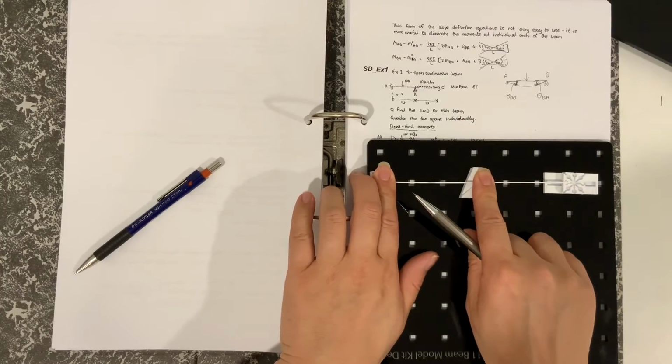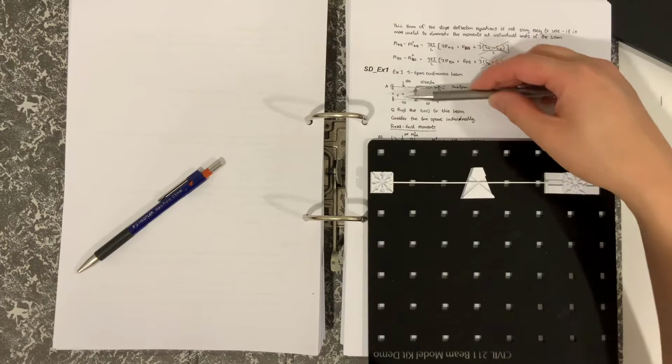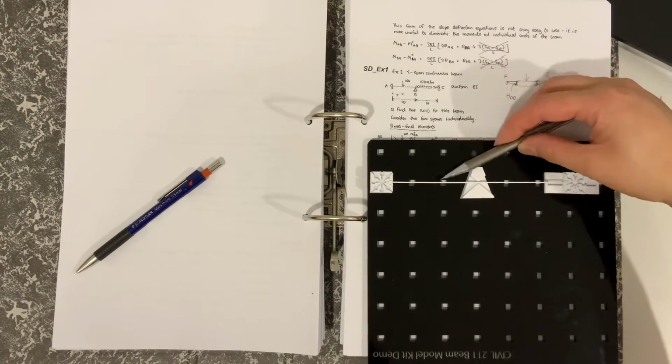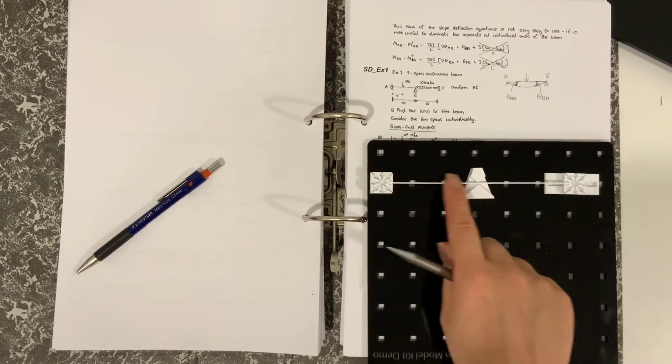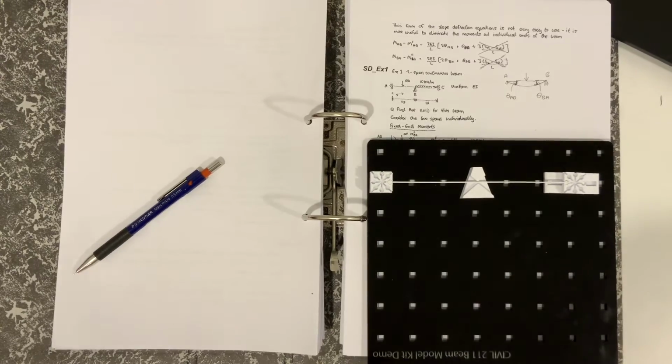So in this case here, we've got 100, so we keep the same span, which would be AB, and we keep the same load. The important thing when you work out the fixed end moment is you keep the same load. If there's no load acting on the span here, then the fixed end moments are of course 0.